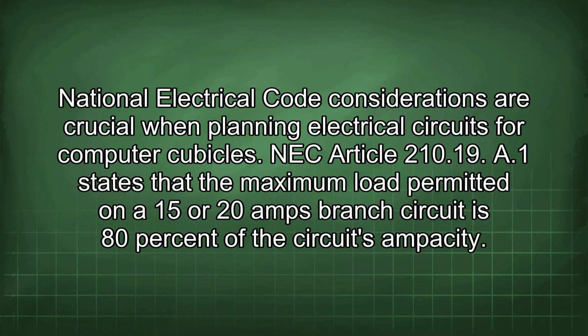National electrical code considerations are crucial when planning electrical circuits for computer cubicles. In NEC Article 210.19, A1 states that the maximum load permitted on a 15 or 20 amp branch circuit is 80% of the circuit ampacity.